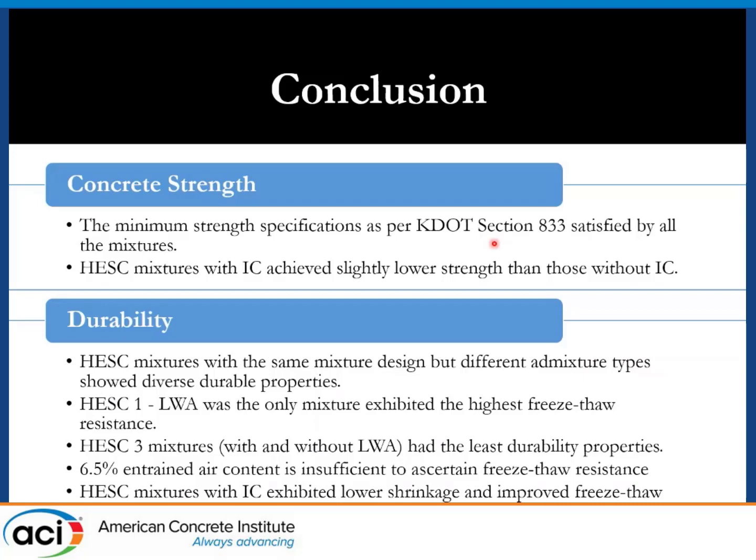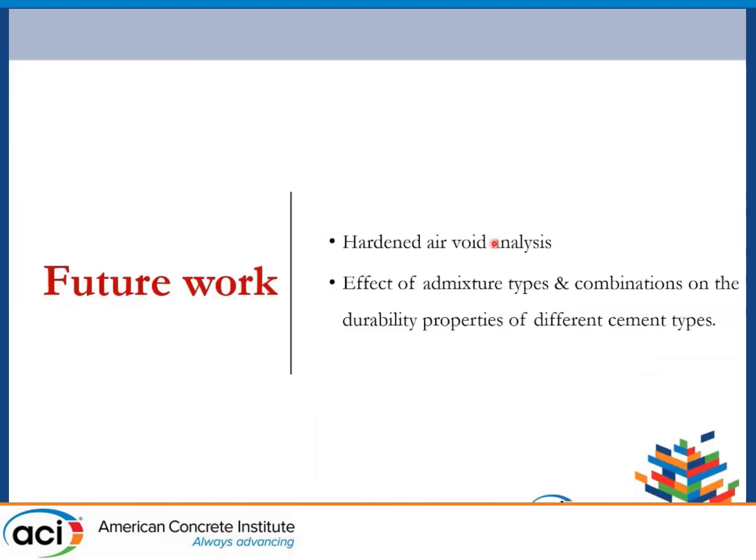That's why we are currently waiting for the petrographic analysis of these samples, which will give us a better idea of what role the admixture combination played on the entrained air void structure. And apart from that, we are also studying whether, in addition to type 3 cement, admixture compatibility plays a major role in other types of cement.